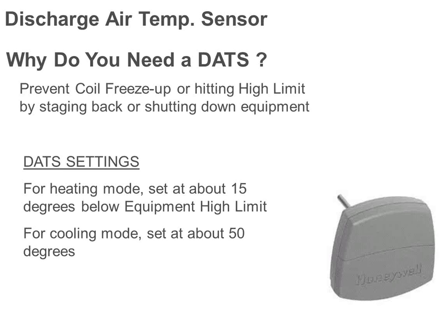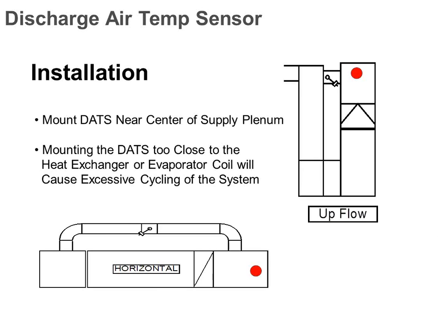The discharge air temperature sensor ideally would be downstream of the bypass takeoff, in the main airflow where it's going to see air movement, not in some corner somewhere. Don't put it in a corner, don't put it on an elbow, don't put it on a bend. I know in the real world where you've got an evaporator coil, a plenum, and a bunch of takeoffs, that makes it a lot harder, but try to get it in a place that's actually going to see air motion. In the perfect world, it would be 3 to 5 duct diameters downstream of all takeoffs and all elbows. I know in the real world that's probably never going to happen on a residence, but that's your goal.